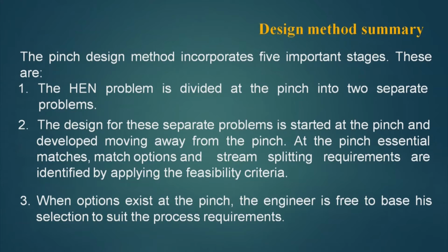When options exist at the pinch, the engineer is free to base his selection to suit the process requirement. The pinch design method allows and offers the designer a lot of flexibility, and according to the process requirements, the designer can place a pinch heat exchanger. That means the stream matching can be done based on the process requirement by the engineer.